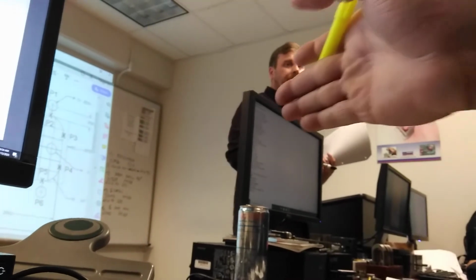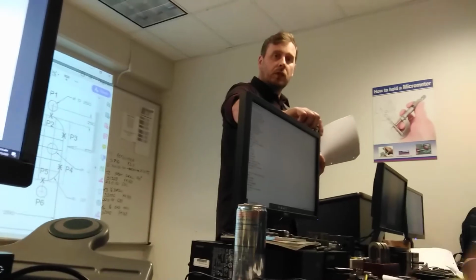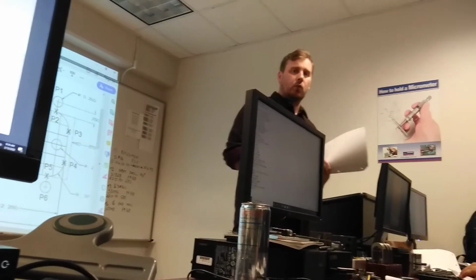Because you're going to rapid onto the part. What just happened to your tool? You broke it. With G1, you're going to cut into the part, which is exactly what you want to happen.